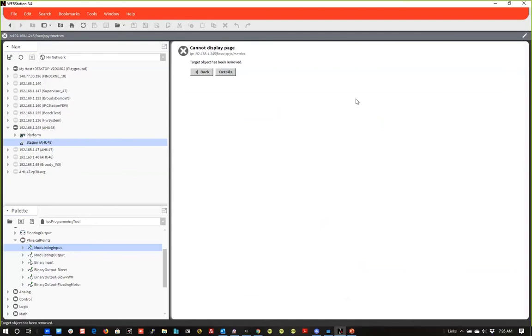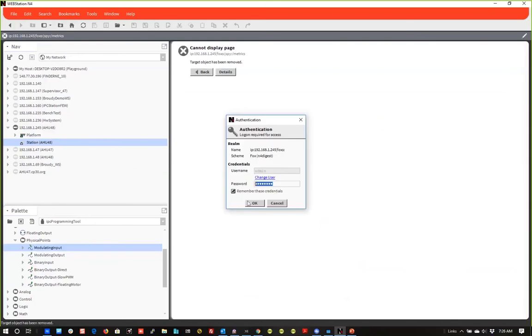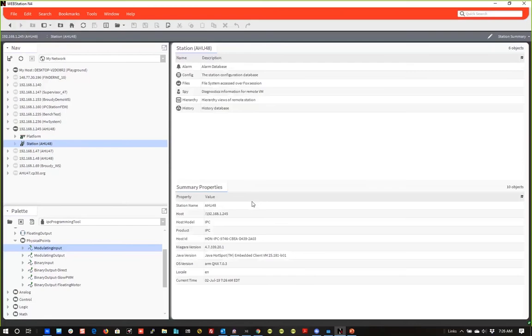Hey, Frank, the other thing I would like to mention that I thought was pretty interesting, and you had called it out on one of your slides, is that they have really beefed up the inputs and the outputs on this controller. Frank had mentioned there's a 16-bit A to D converter now instead of the 8-bit that we had on a Spyder. So that means the resolution is double or more on reading inputs, and the 0 to 10 volt analog output as well.